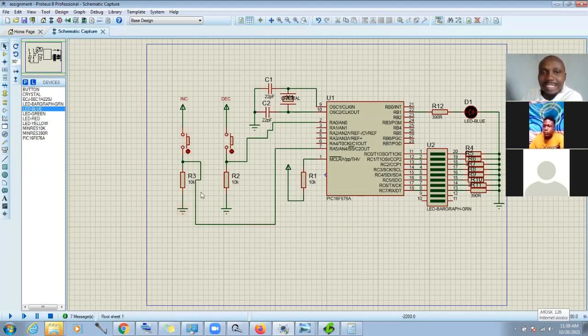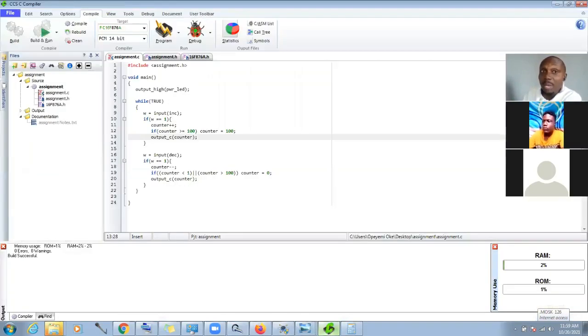So what you should do in this case is create something called a debounce switch or a debounce option. Debounce is such that every time you press the button, you create a delay, enough time delay for me to have pressed this button and released my hand. So you either use a delay immediately after the instruction to scan when the button is pressed. The other thing you can do is test when the button is released, which is what I ascribe to most times.